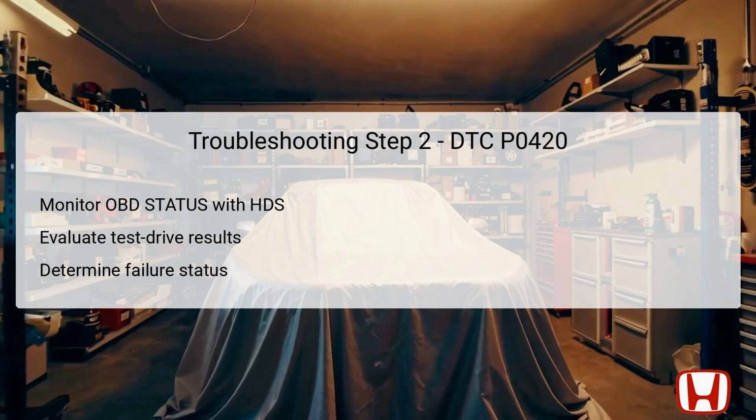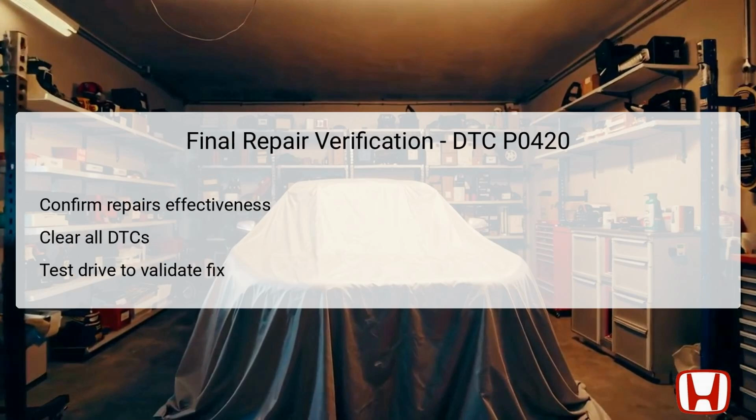If a snapshot of the onboard data at the time of the DTC occurrence is available, attempting to replicate the situation while monitoring the conditions provides invaluable insights. In the case where the HDS indicates out of condition, ensuring to meet all testing parameters is essential for an accurate diagnostic conclusion. Upon completing the necessary repairs for DTC P0420, confirming the effectiveness of these repairs is essential.